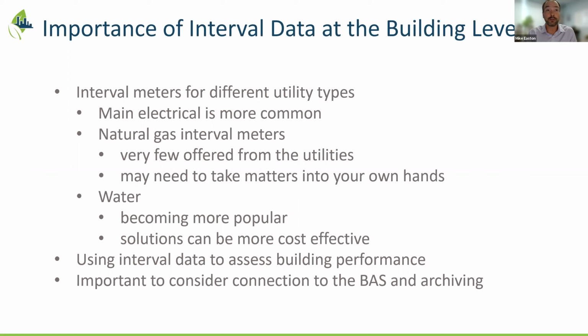When we are able to integrate, and the City of Toronto is a good example, what we're able to do is purchase and install new modules that go on the existing meter and provide a pulse output. The city does need to be involved to reseal the meter after that installation is done. And obviously there's some labor necessary to connect that to an energy management platform.